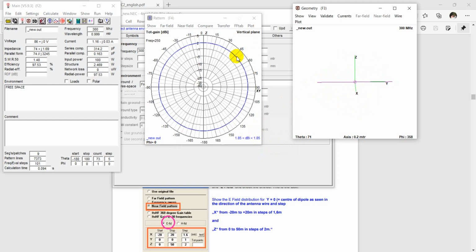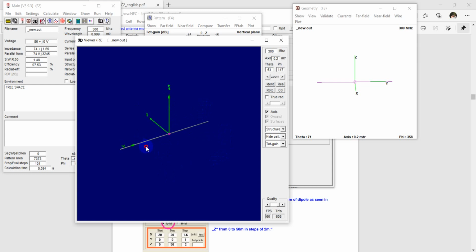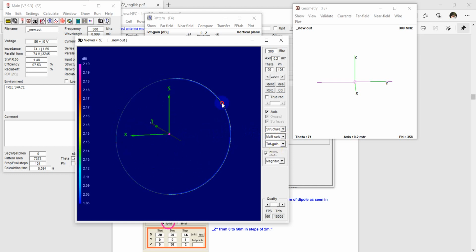The antenna is designed in this pattern, and when we tap the 3D edition, we can see the antenna parameters. If we want to see the segments, you have to choose this option and put the segment to show this segmentation. You can see the feed is almost in the center. If you want to see the radiation pattern, then you have to set the middle option to multicolor. You can see the radiation pattern, which indicates the radiation of this antenna.